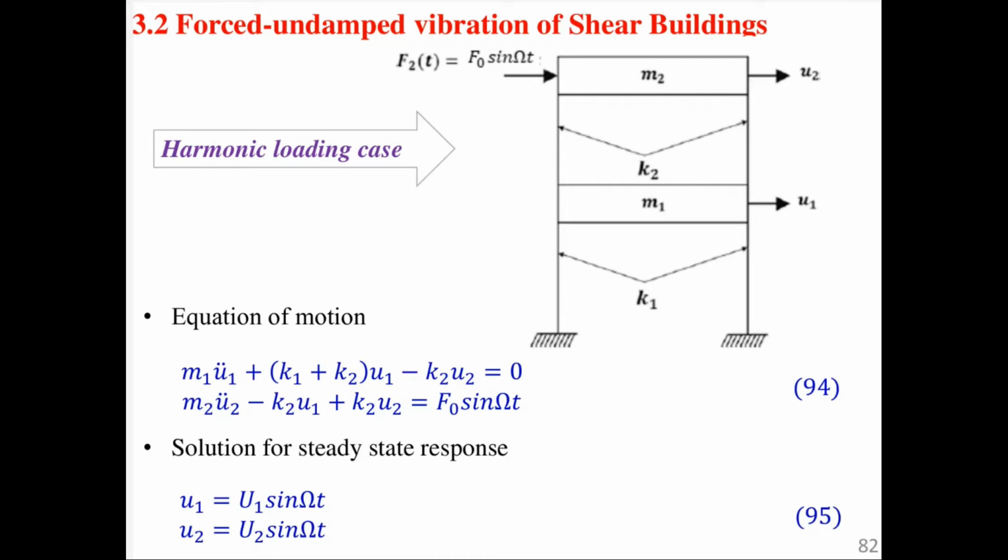Free undamped vibration is kind of an ideal scenario, somewhere like there is not even an atmosphere, because there is not even fluid drag as a result of airflow. So we are moving from the simplified ideal case towards the more realistic but complex case. And again, we are even considering just a 2-story or 3-story building, because the number of equations involved continues increasing as the number of stories or degrees of freedom increase.